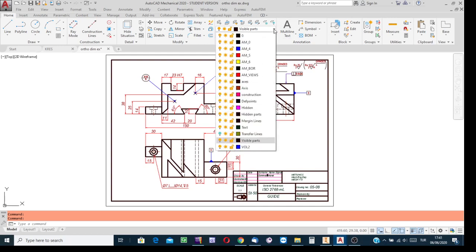Well, this will allow you to see the transfer lines. Use the filtering technique, turning the visibility of the things in the layer on, so that we have the transfer lines. Okay, transfer lines, I am sure in this layer I have the transfer lines. These are the straight vertical or horizontal lines.